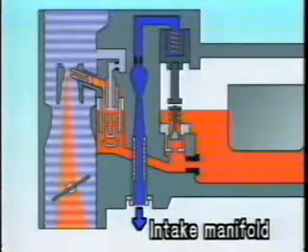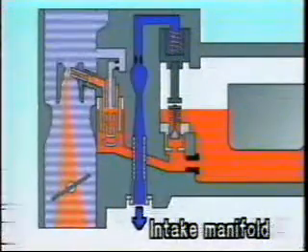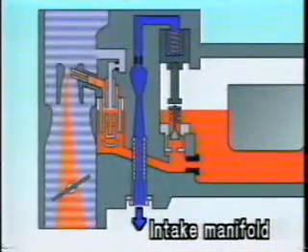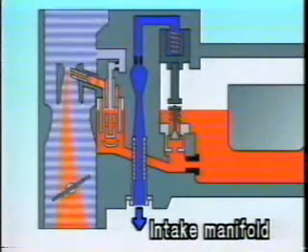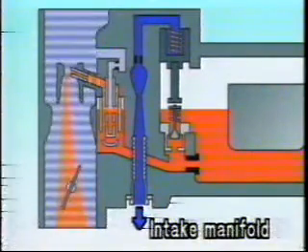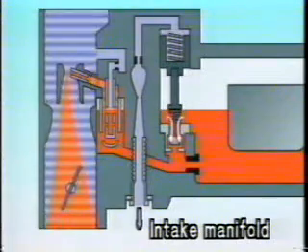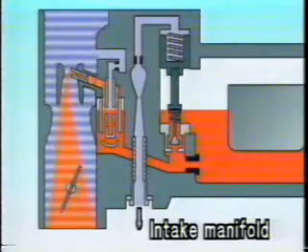When driving at a constant speed with the opening of the throttle valve small, the power valve is closed due to the high manifold pressure. When a big increase in power is needed, the driver depresses the accelerator pedal, thus opening the throttle valve wide. This causes a decrease in the manifold pressure. When the pressure in the manifold falls below the standard value, the spring pushes down the power piston and opens the power valve. The flow of fuel becomes less restricted, and the fuel is delivered from the main nozzle.